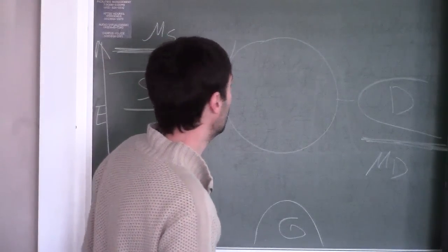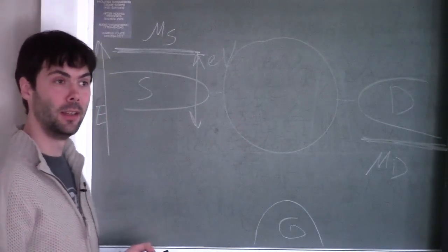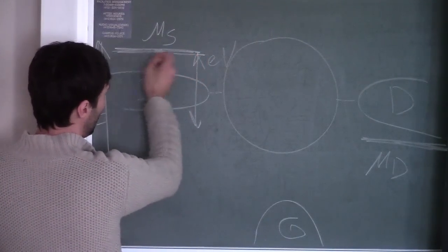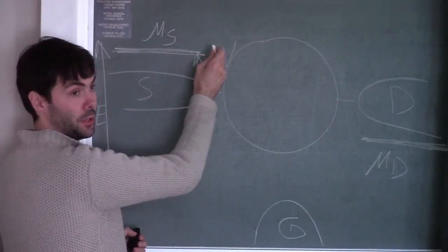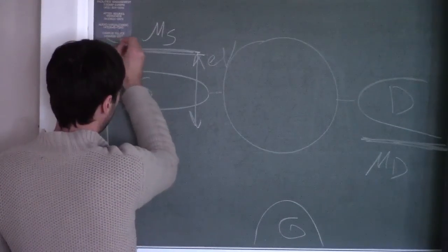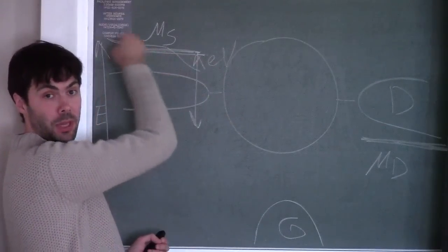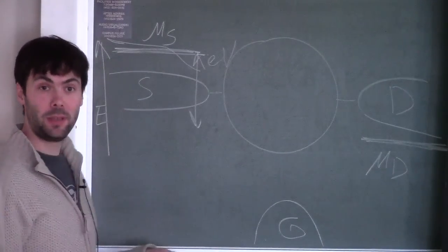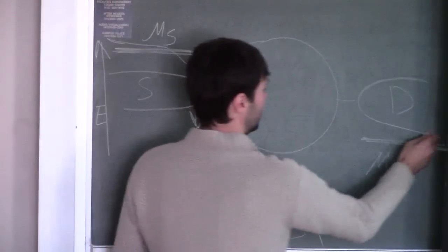Okay. Now, kT, this energy scale: if we now plot the occupation of electrons around this chemical potential, what kT does is it will create a little bit of electrons above the chemical potential and some empty spaces below. It will smear this distribution, and it will become a Fermi-Dirac distribution at finite temperature in the source, and same in the drain.